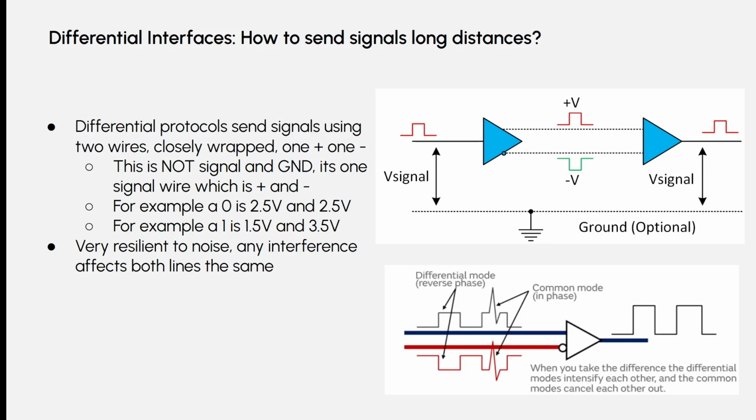And it's not obvious just sort of thinking about it, but it just turns out that in reality, when you make really long wires that only go between 0 and 3.3 volts, any sort of interfering radio frequencies, like even from your cell phone, from a walkie-talkie, can easily disturb those signals and cause false ones, false zeros, interrupt your data transmission. And if you're transmitting a lot of power or data over those lines, you can cause interference and potentially cause other devices not to work properly.